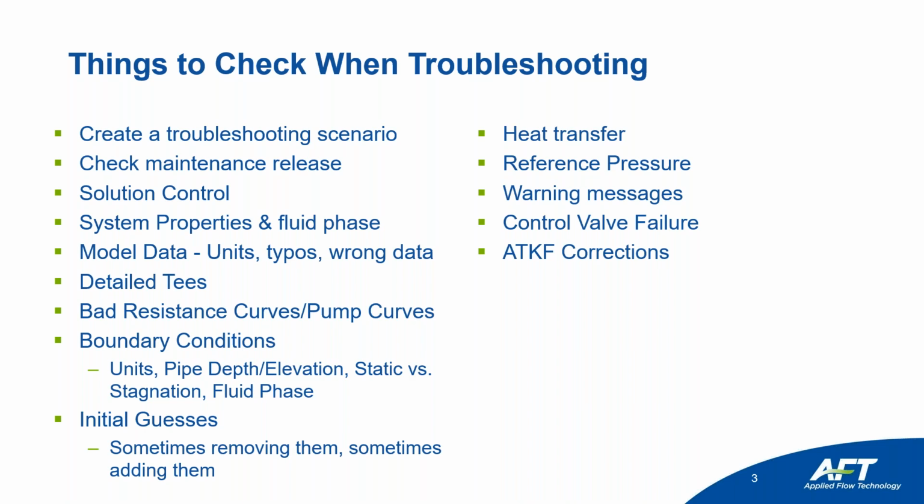The reason why this is really important to add in correction factors is because the K-factor loss models that are standard, developed by Crane, Idelchik, and Miller and whatnot, were developed under turbulent Newtonian flow conditions, and the loss models may not directly apply to laminar flows or non-Newtonian fluids.